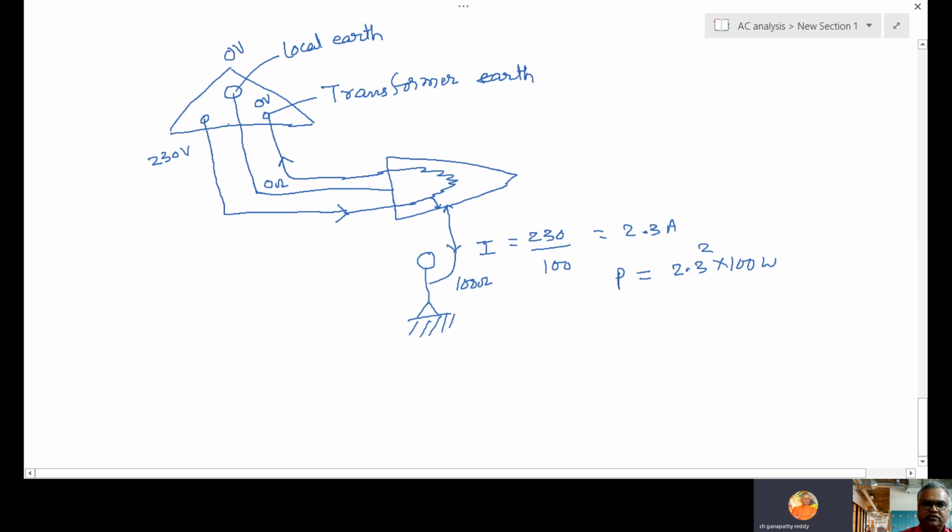So what is the best safety? Thicker. Not only thicker, it should be longer. If it is a short length, when we plug in the 3-pin, there is a scope that it might not contact properly internally. So to ensure it is contacted perfectly, a longer pin is used. So everything has a science behind it.